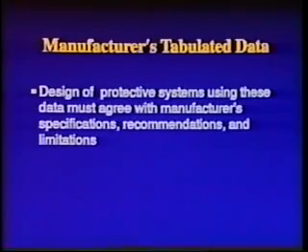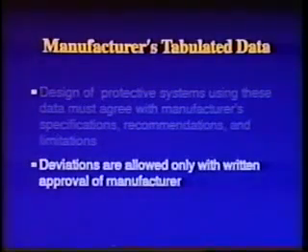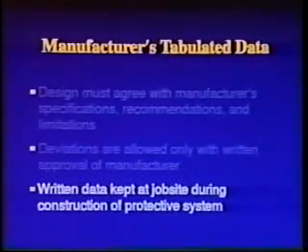Design of support, shield, or other protective systems using these data must agree with all specifications, recommendations, and the limitations issued or made by the manufacturer. Deviations are allowed only with the manufacturer's specific written approval. These data are to be in written form and kept at the job site during construction of the protective system.